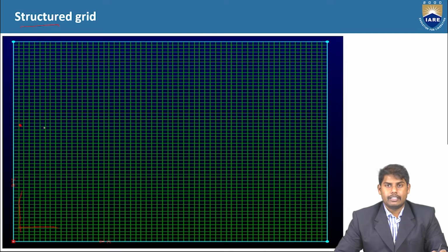And in this picture you can see that what we have is a structured grid. Why we named it a structured grid is because you have cells like a quadrilateral, which has four sides. Here it can be a square or a rectangle. And the main thing is that the grid will have x lines and y lines, and no two x lines will meet each other at any point for a structured grid. If they meet and cross, then you will have negative volumes and you will have an error when framing the grid.